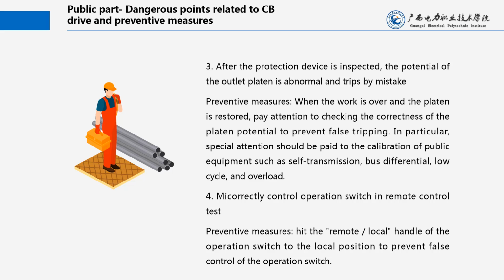4. Mistakenly control operation switch in remote control test. Preventive measures. Hit the remote/local handle of the operation switch to the local position to prevent false control of the operation switch.